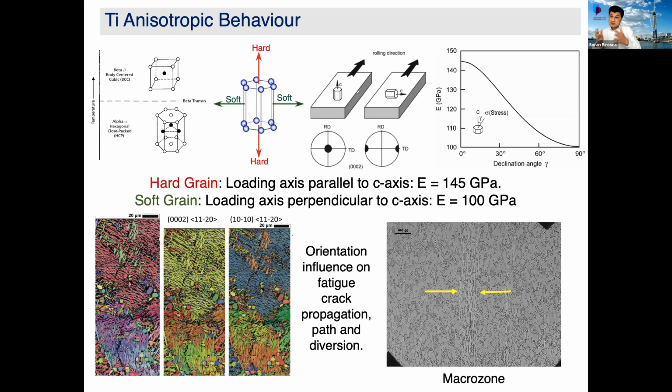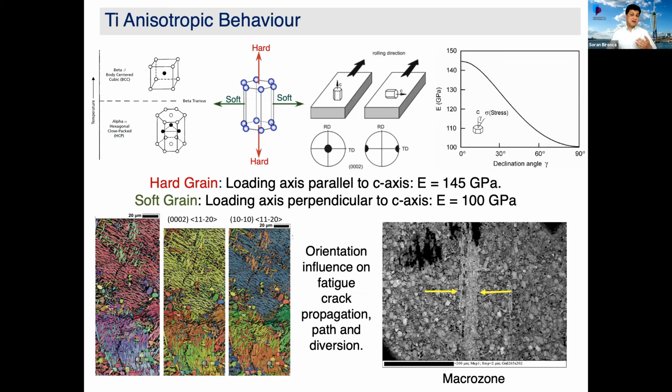And that's not only affecting the energy during the deformation and rolling and so on, but even in service you will have the same problem, because, for example, if these lamellae are oriented for the basal and prismatic slip activation, I don't want to go through this, then the crack will be very easy to go through the lamellar structure.